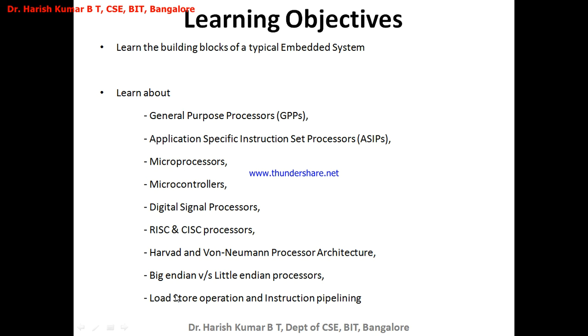ARM basically comes under the load and store architecture because, for the operations which you can do using the ARM instruction set, both the operands must be inside the register. That means you cannot perform the operation if one operand is in a register and another operand is directly in the memory. You have to get both the operands to the registers, and then you can perform the operation. Now, register memory class architectures allow the operations to be performed even if the operands are available in the memory. One operand in the register, another operand in the memory, you can perform the operations. But when I say load and store architecture, the operations are performed only on the registers. So it is necessary for you to get the operands which are in the memory to the registers, and then you can perform any data processing operation. So that is what we look at here.